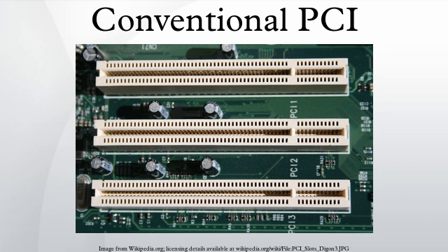Note that most PCI devices only support a limited range of typical cache line sizes. If the cache line size is programmed to an unexpected value, they force single-word access. PCI also supports burst access to I/O and configuration space, but only linear mode is supported. Transaction examples: this is the highest possible speed for a word write burst, terminated by the master.